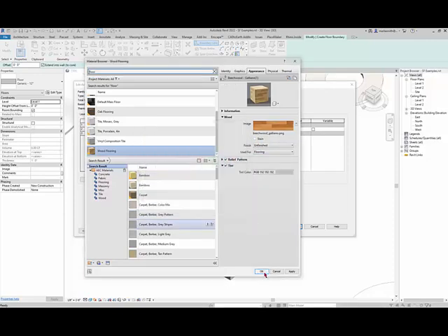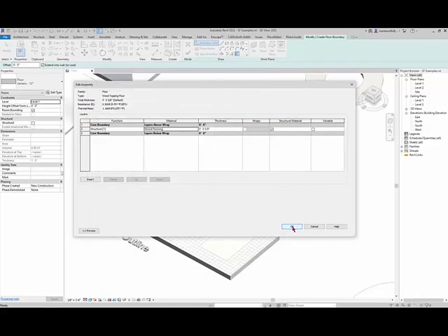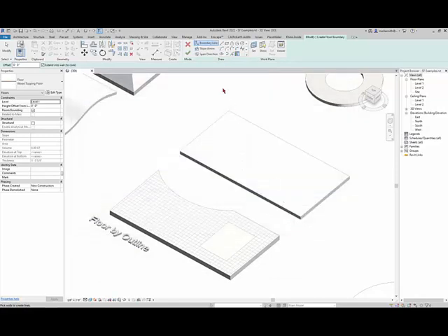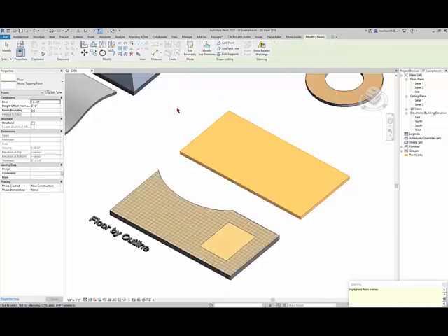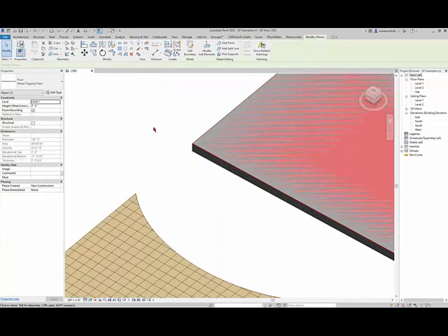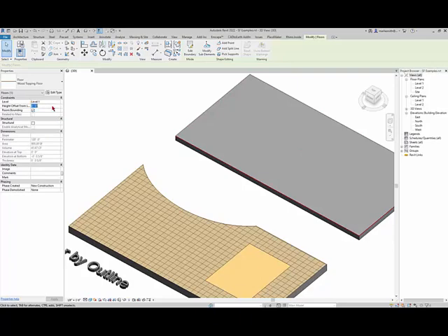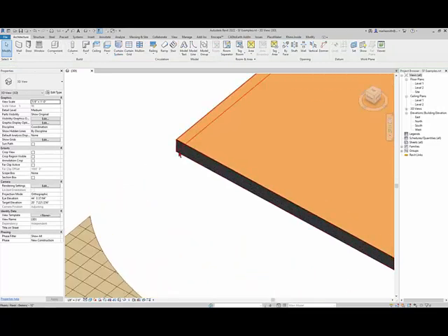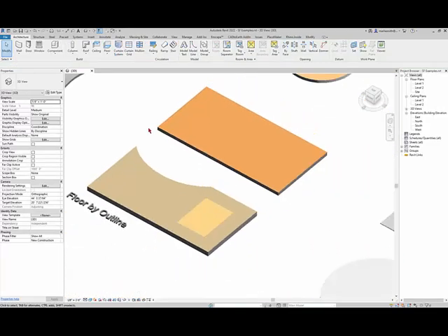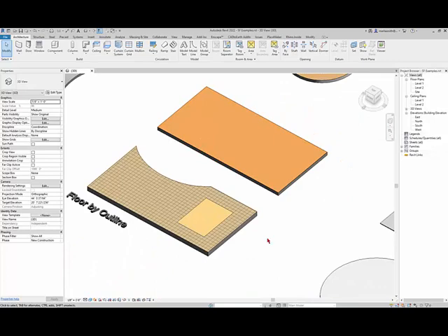Okay, click OK, click OK, click OK, and now I could come in, and if I do a pick line, I could pick around the edge of this and hit the big green check, and I just need to make sure that I set that floor height offset to 5/8 of an inch. So now I have two floors, one subfloor and one top floor. So that's split face, a couple of different options for creating floors. I think that for right now is okay for this part.